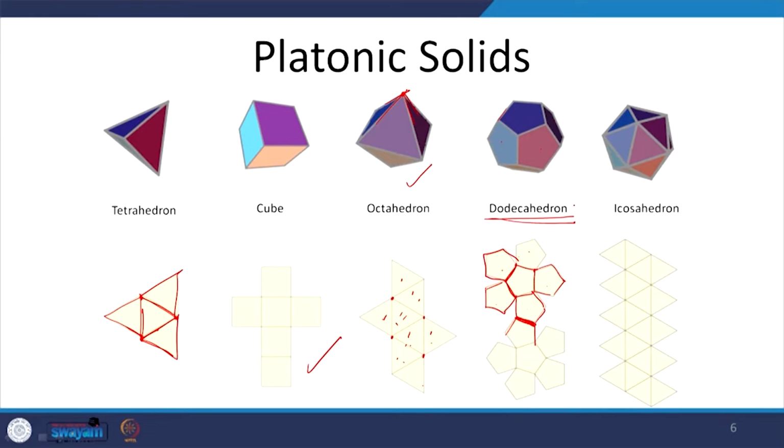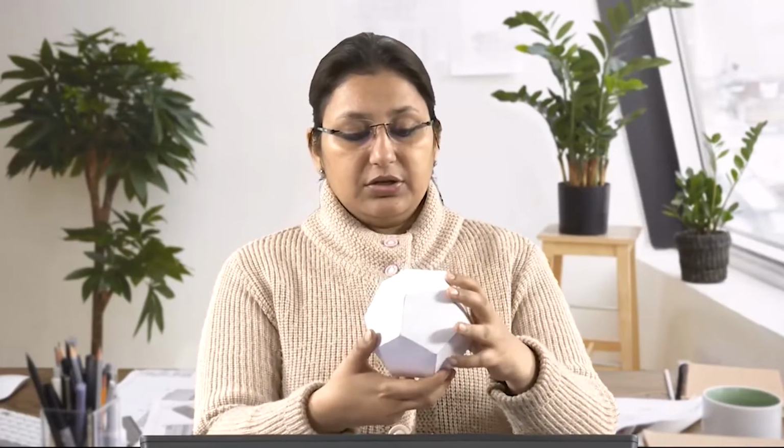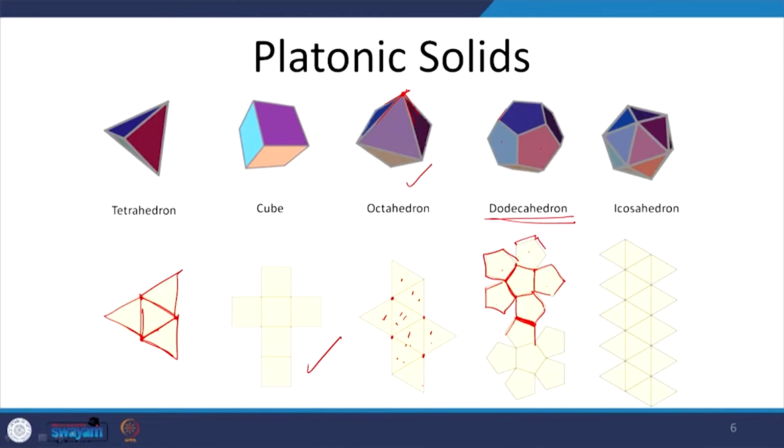If you look at this solid, which is here in my hands, we have developed this dodecahedron using the pentagons. So the base surface is a pentagon. We start drawing this pentagon, and you keep developing the pentagonal surfaces, and once you put them all together, in case you have to develop it, right now it is only what will be seen on this surface. If you have to make space for sticking it together or welding it together, you have to have some little extra pieces, which is what we will draw along. So we know how these surfaces are going to be joined. So probably we will have these small jutting out surfaces which will be drawn along.